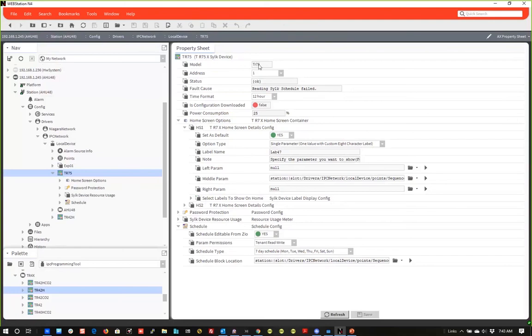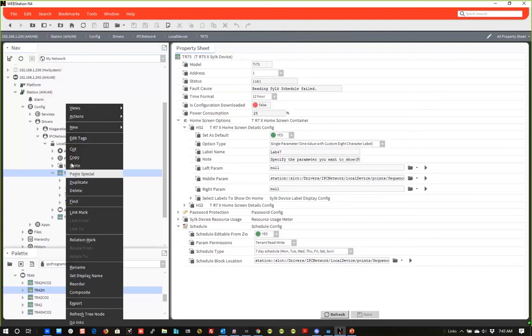And then once you're finished configuring those, you're going to come in here and say action. If you added a bunch of components for a ZIO but didn't tell it which ZIO it was connected to, and you only have one ZIO, you can come in here and say attach unassigned parameters. So all of those, the room temp set point, the system mode, all those blocks will automatically get assigned to that ZIO.